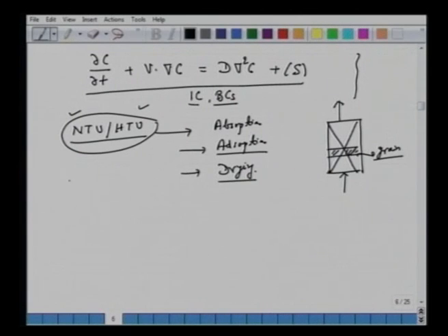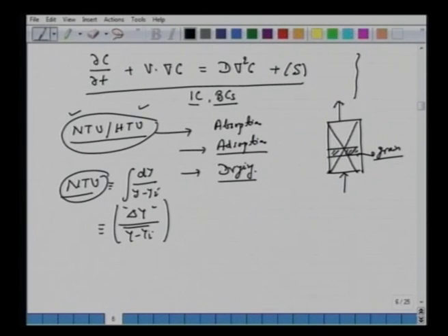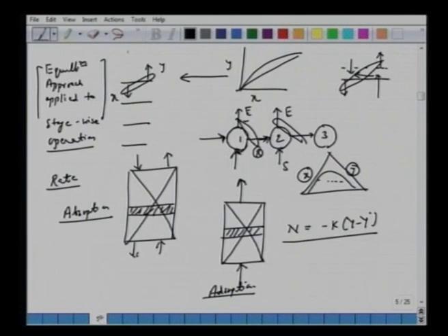Okay, we said that NTU, a very common definition we should remember, is nothing but dy over (y minus yi), but we should look at it fundamentally, that is nothing but the enrichment over the average driving force per mass transfer. Alright, so you bring in this NTU, number of transfer units. You are saying that this packed column has certain physical or hypothetical NTUs. Each transfer unit has a certain height, which is a function of mass transfer coefficient and a, the surface area per unit volume. Unlike, if you go back to the previous slide where we talked of this stage-wise approach, here there is no Km.